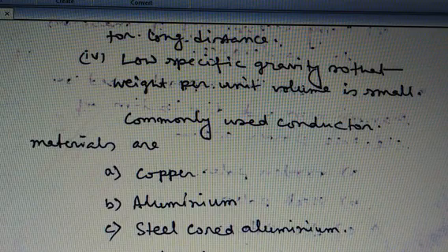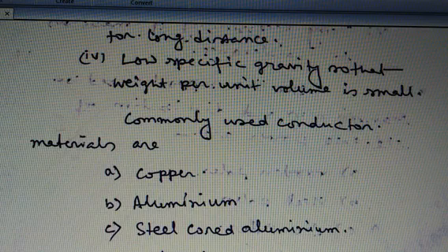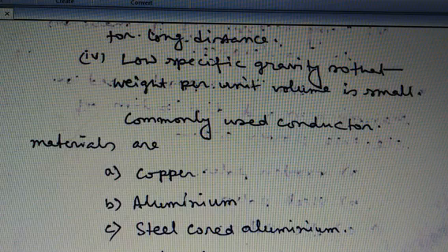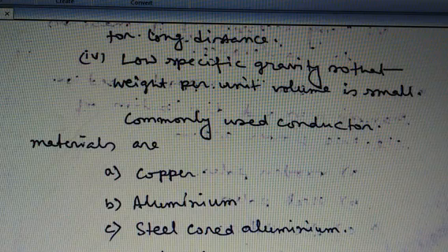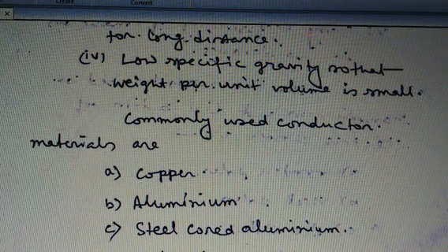Therefore, cadmium copper conductor can be useful for long spans. However, due to the high cost of cadmium, such conductors will not be economical for lines of small cross section, that is, when the cost of the conductor materials is comparatively small compared to the cost of the supports.